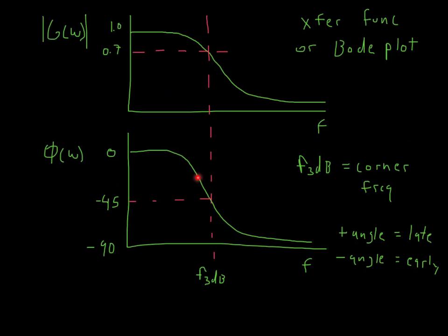It comes early, basically. So what we have is the output we see gets ahead of the input. All right, it doesn't violate causality. It's not like the actual speed of the signal gets there, but compared to the input, the phase is negative. All right, and so that means that we have an early arrival of the output compared to the input.